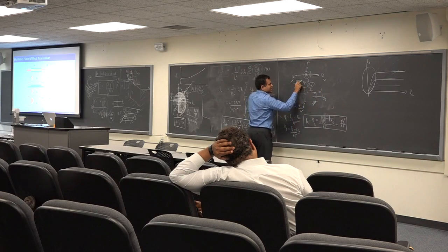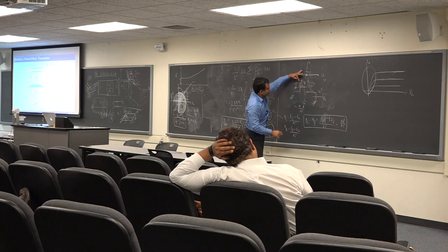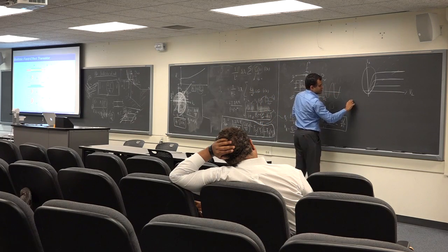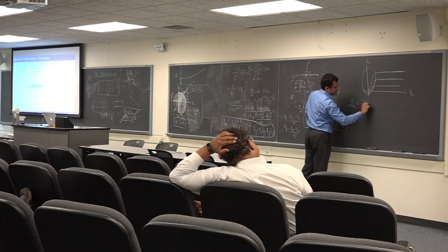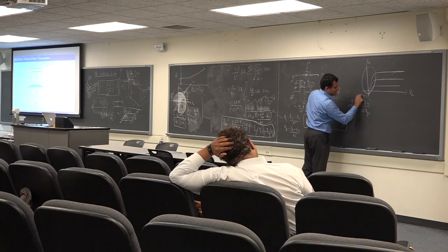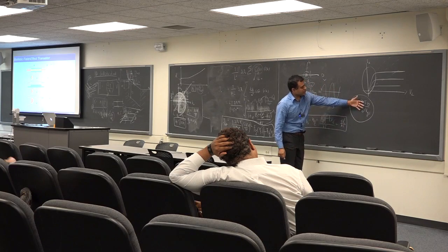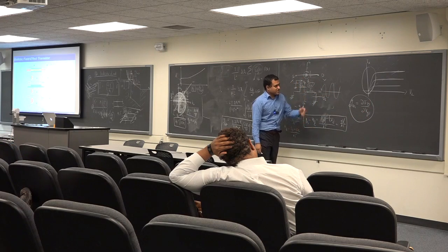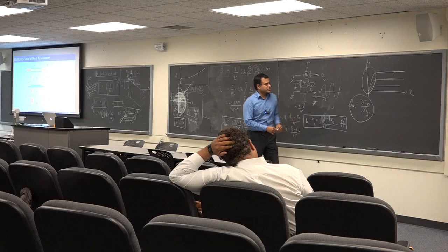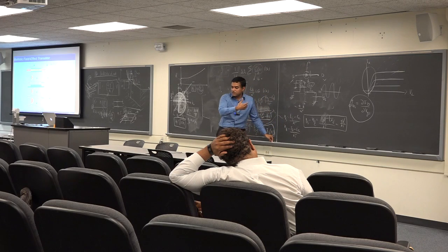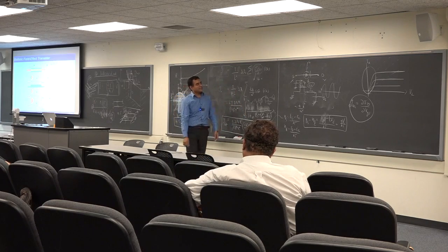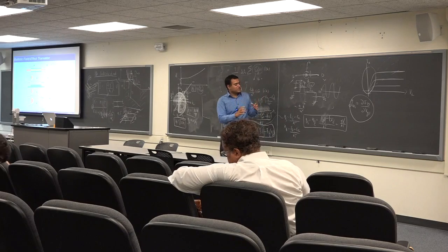That's a DC gain, which is really not terribly important as much as if I have an AC signal, a very small AC signal riding, and the output here goes up by a large amount. This factor in transistors is called transconductance, and we will discuss this in the next class. I'll just stop here, okay? It goes as a derivative of drain current versus the gate voltage. So that's the transconductance, which has units of 1 over ohm, or Siemens. So we'll look at that. The larger the transconductance, the more the gain, and that's always a quest. You want more gain, more on-off ratios, smaller voltages for switching, and so on.